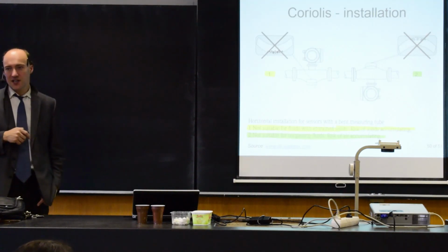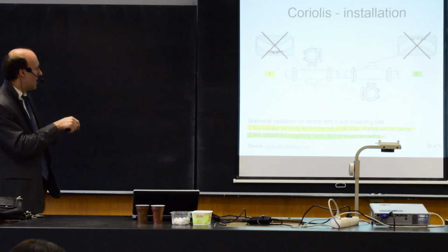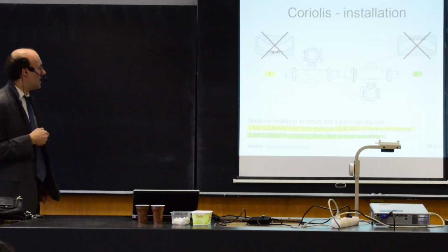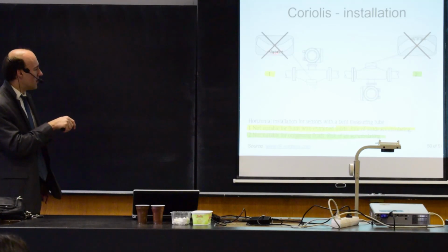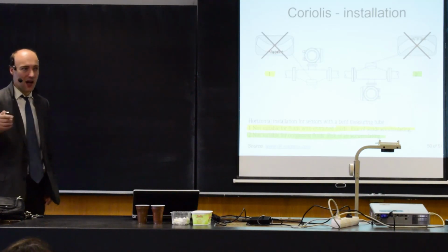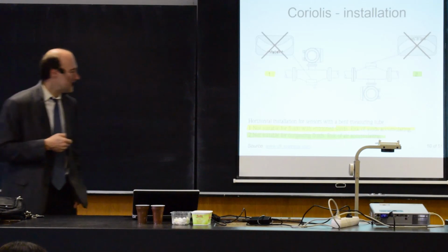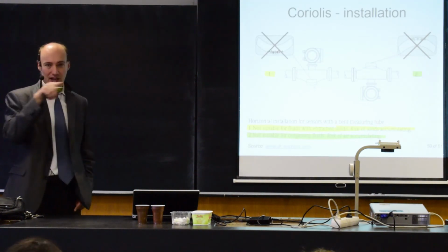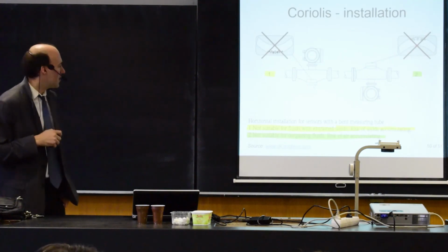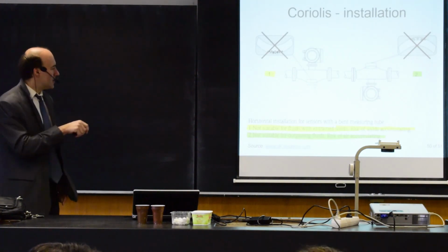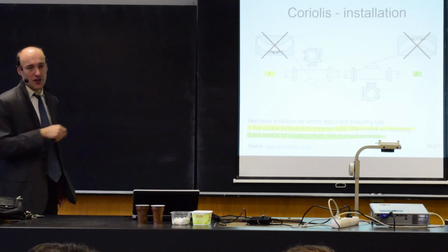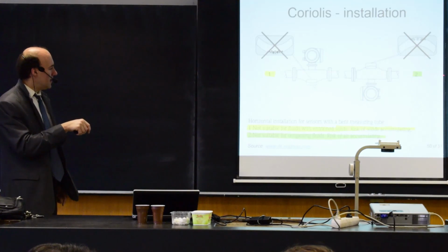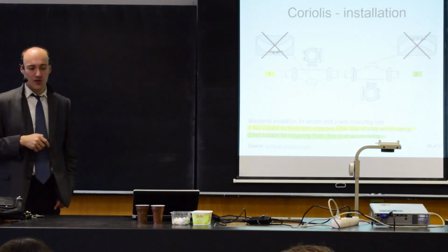The reason is sediments, because if you have sediments in the pipe, it will change the properties of the system, and plus there is no way how you can remove it unless you apply high flow rate to flush it out. If you install it in this way with the bending facing up, it's also wrong, because then you may have the same problem with the bubbles. So do not install the Coriolis flow meter in a horizontal pipe.